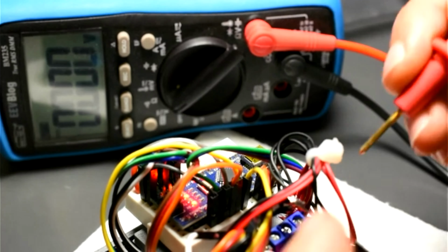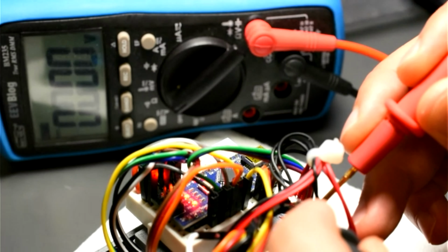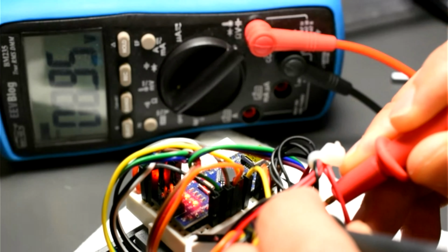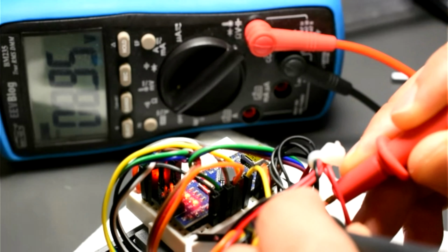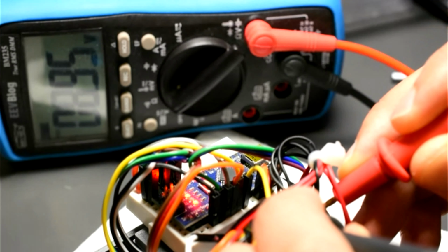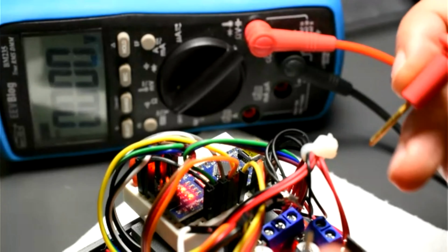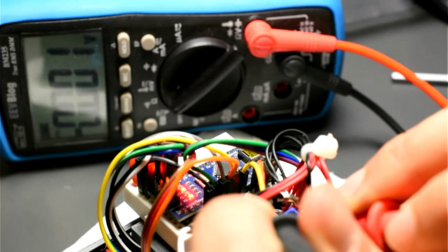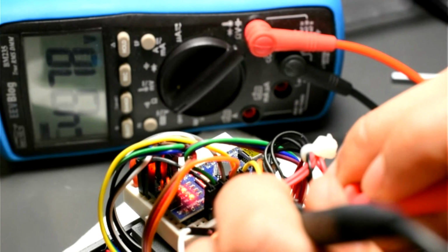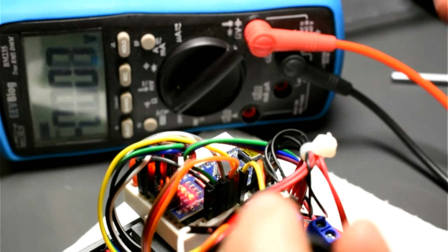So as a test, I will actually probe the positive and the negative of where the battery is connected to, and I should get just over 9 volts. Just under 9 volts. Gotta play me like that. 8.95, that means these batteries are just starting to lean off in terms of capacity, unfortunately. 8.95 volts, and then we can see over here, we should get 5 volts. 5 volts. It's negative because I have the switch the pins around.